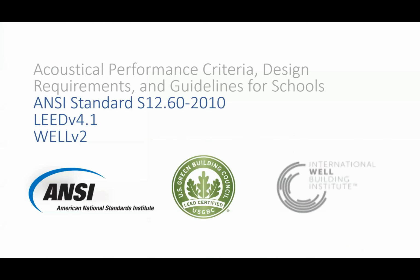Yeah. So besides the code criteria, which would need to be addressed in Florida schools, and it is in the IBC code as well, depending upon when other states adopt that, it may be in other states besides just Florida, but Florida requires it now. And there are these other criteria that can be looked at. There's ANSI S12.60, which is one of the main standards for classroom acoustics. Then we have LEED criteria and WELL criteria as well.